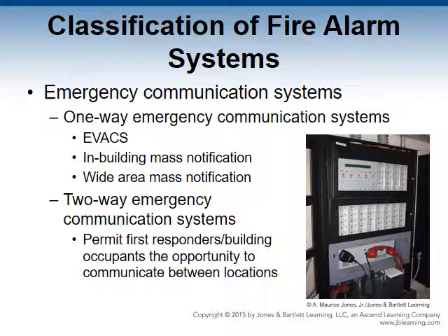Fire emergency command center and high-rise fire alarm system packages house the fire alarm control and announcement panels. The command center must be separated from the remainder of the building by 1-hour fire-resistance-rated fire barriers.